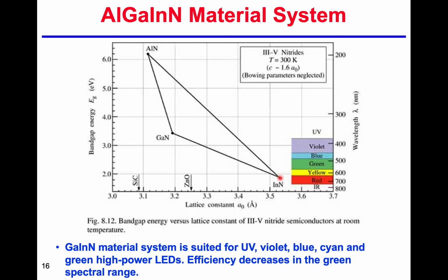The second exciting thing is actually in this diagram, that is all the red band gap. Okay, so what's the problem? The problem is actually we cannot find a suitable substrate. Silicon carbide is here. Zinc oxide may be okay, but we also need to consider the crystal structure. And so that is a problem. We don't have the suitable substrate for the gallium nitride system.